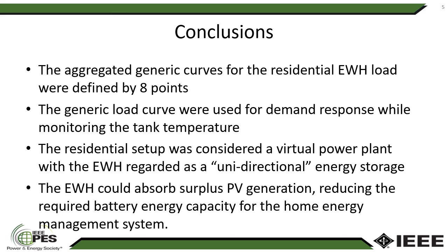Conclusions. The aggregated generic load curve for the residential electric water heater load was defined by 8 points. The generic load curve was used for demand response while monitoring the tank temperature. The residential setup was considered a virtual power plant with the electric water heater regarded as a uni-directional energy storage. The electric water heater could absorb surplus PV generation, reducing the required battery energy capacity for the home energy management